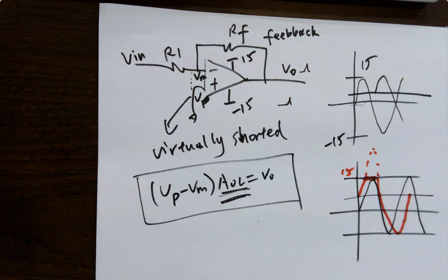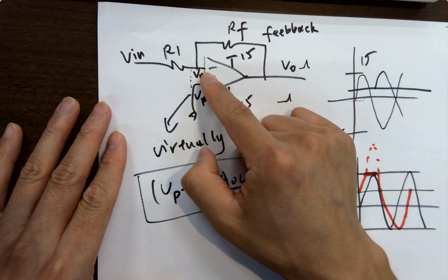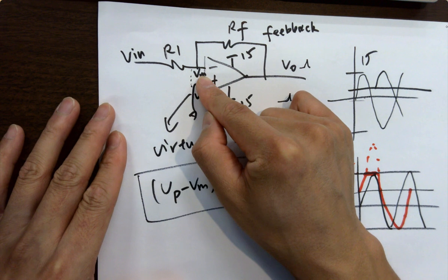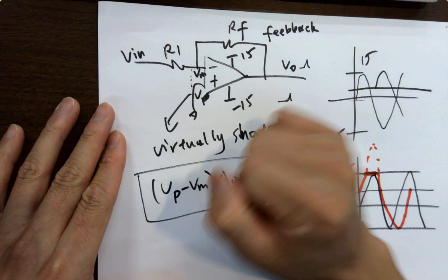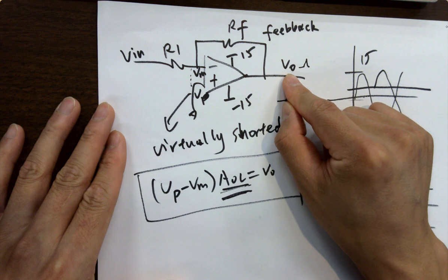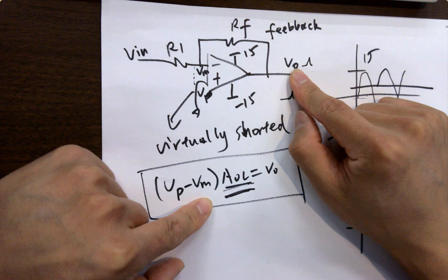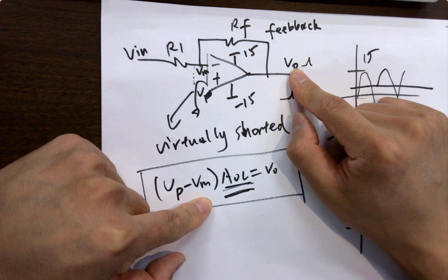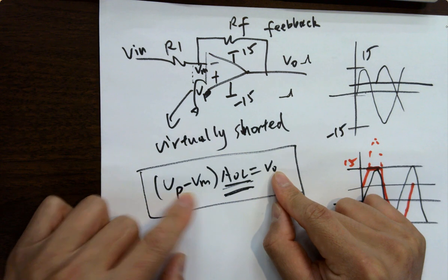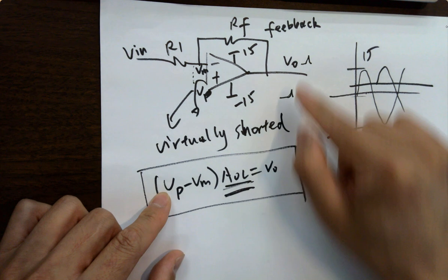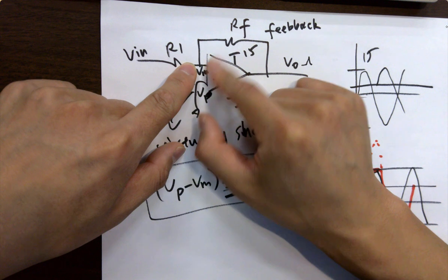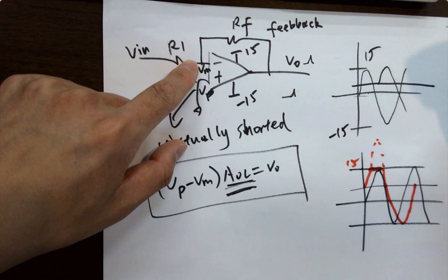This brings up another super important and common interview question. Isn't there going to be voltage drop across the feedback resistor though? It had voltage drop already, right? But the thing is, let's see how this is making this higher. Previously you don't have anything over here, because they were equal. If they are equal, what is this? 0. If they are not equal, this is larger, and you are getting a positive voltage. So this voltage will be positive, not 0 anymore.